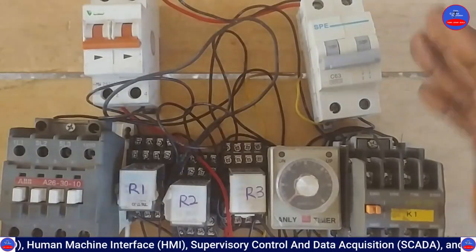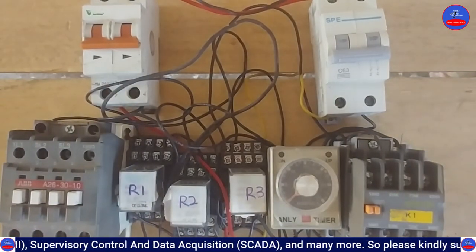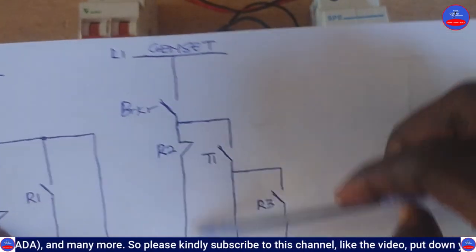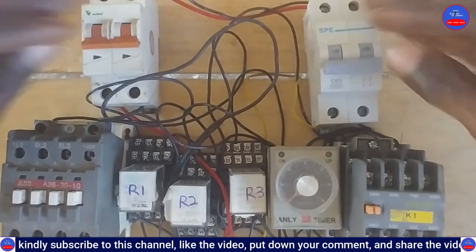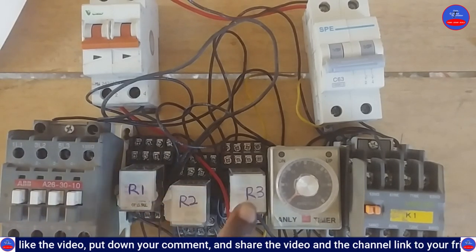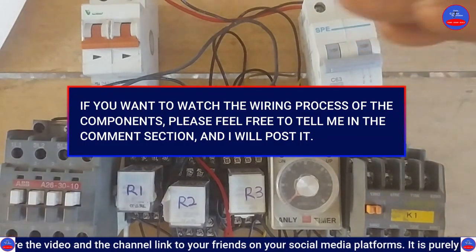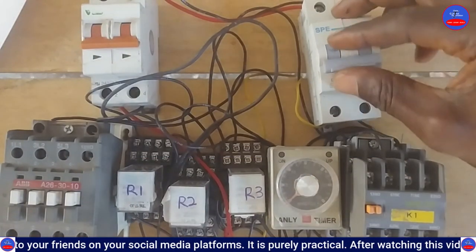So this is the complete wiring. Now let's assume, as I said earlier in the diagram, that our utility power is off and then we are coming to start the genset. So this is the genset breaker, the utility breaker, the utility contactor, utility relays, genset relay, genset timer, and then genset contactor. We already have the genset on, but it will delay for some time before the output will switch on.